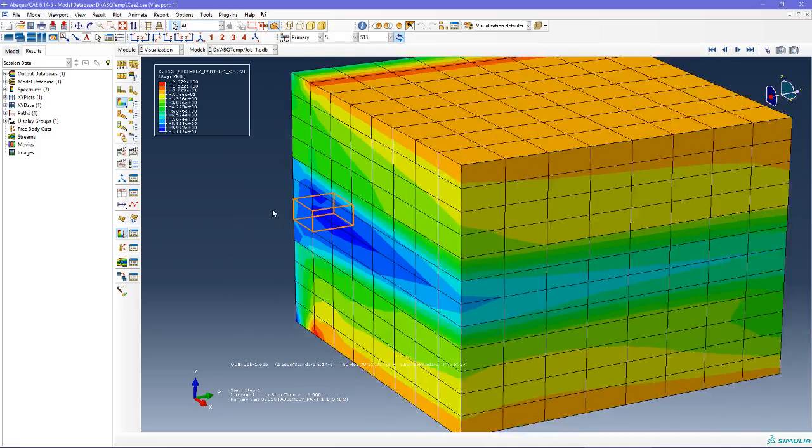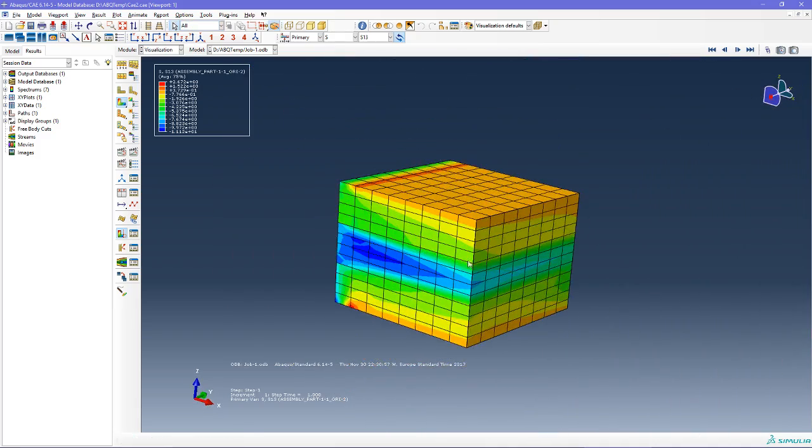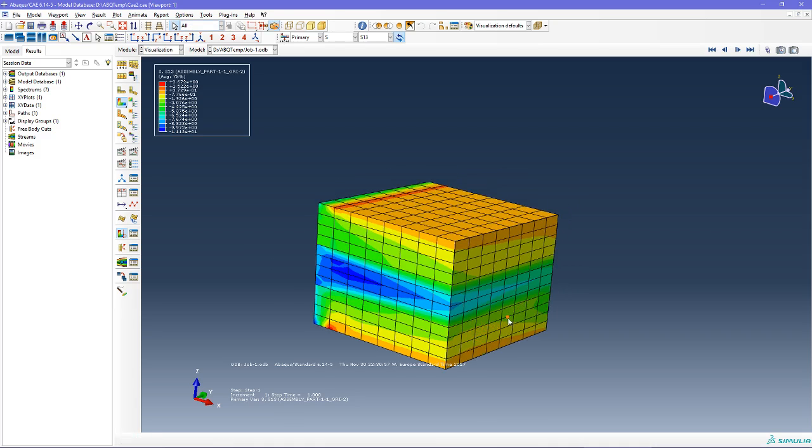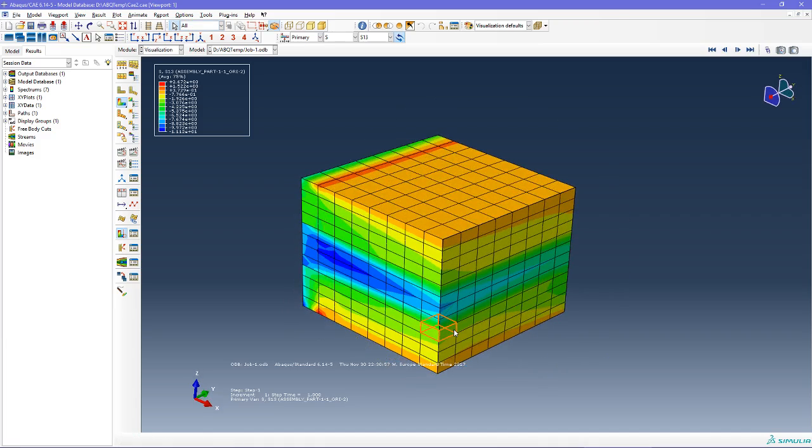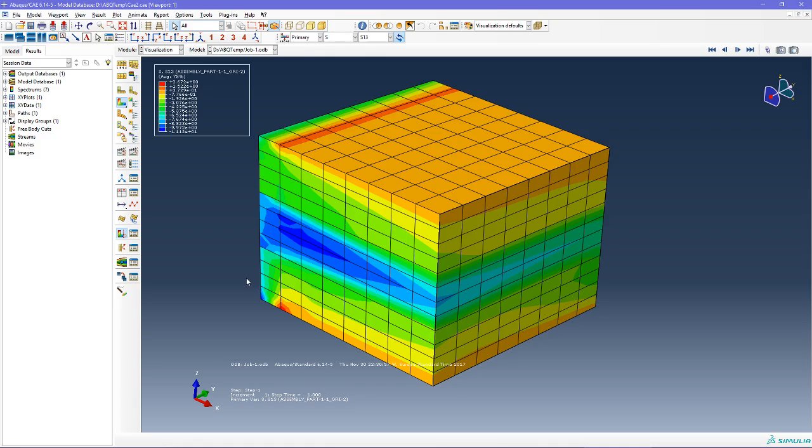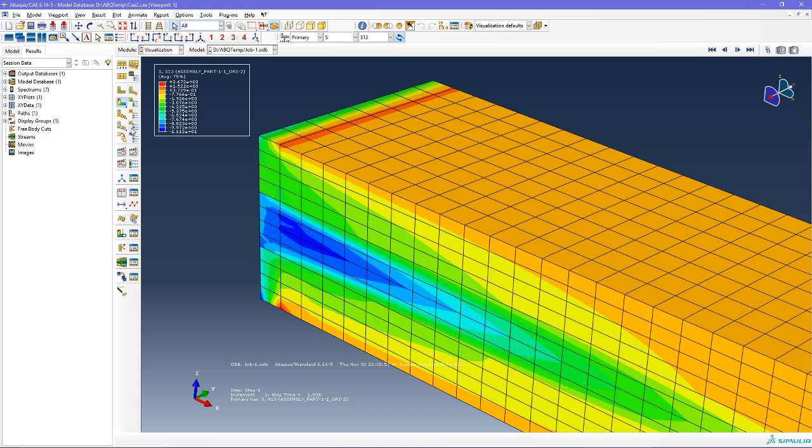And some friends may want to ask that, let's say in ABAQUS, when you are building a composite layup with the layup manager, you can visualize the structural layup scheme. But for brick elements, we can't do that in the same way. What we can do is plot the material orientation here in the post-processing part.